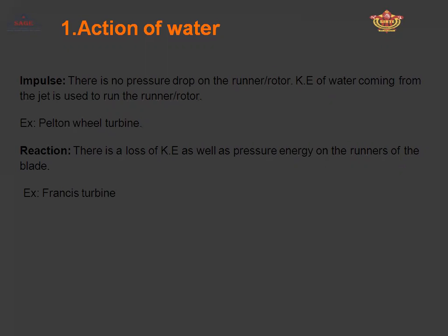There is no pressure drop on the runner and the rotor; the kinetic energy comes out from the water side, and the jet is used to run the runner or rotor. There is no pressure drop.